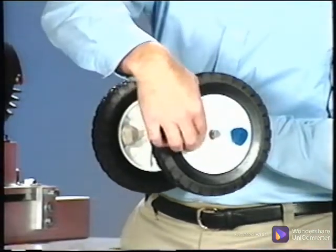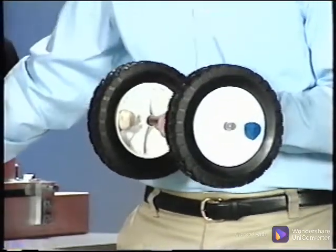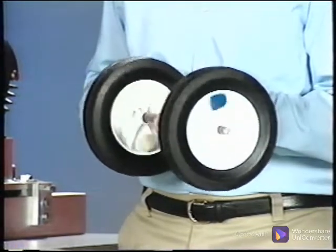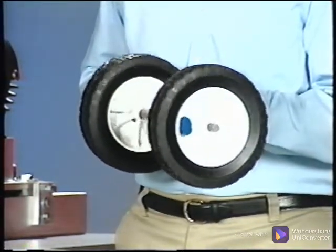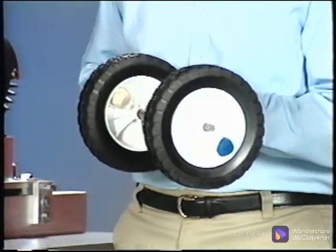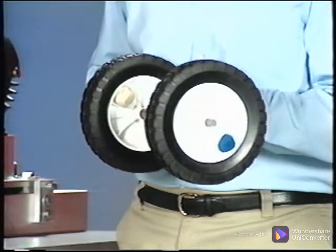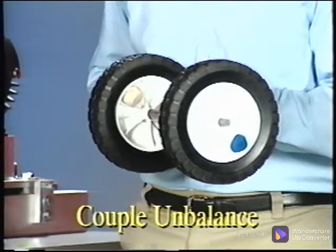Another type of unbalance may be statically balanced so that the rotor will stay at any position when it is at rest, but when it is spinning, it exhibits unbalance. This is because each end of the rotor is unbalanced. The unbalance amount is the same at each end, but in the opposite direction, so that the rotor is balanced while it is still. This type of unbalance is called couple unbalance.